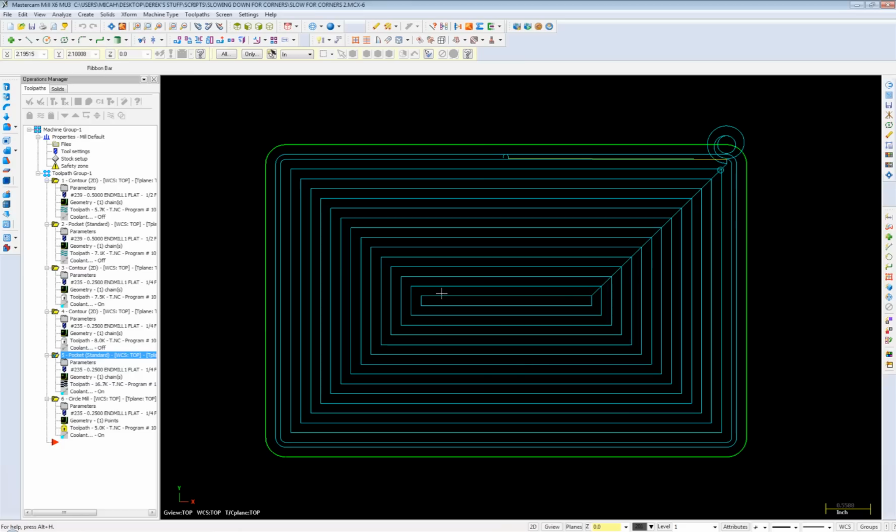Go ahead, Mike. I agree with you, because if it's file dependent and you've got splines all over the place when they should be arcs and lines, then yes, you have to simplify. A golden rule for me is that if I bring an IGES file in and have to use that wireframe, I delete duplicates and then simplify before I even start. When you bring in a solid, you don't get duplicates; it minimizes how many splines you get. You will always get the minimal amount of splines when pulling wireframe off of a solid.